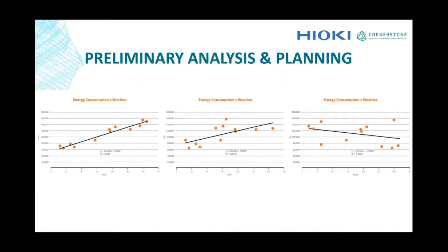And then as I spoke earlier about the regression analysis tool, it's basically to understand what is a major driver or variable that is driving consumption across the building. So here in UAE, most of it is attributed to the weather. So we correlate weather data and the energy consumption, or the electrical consumption, or the chilled water consumption.